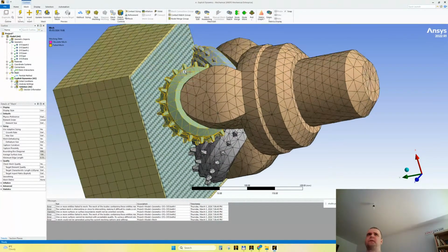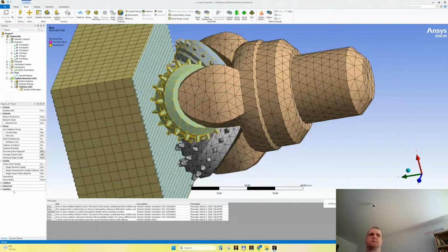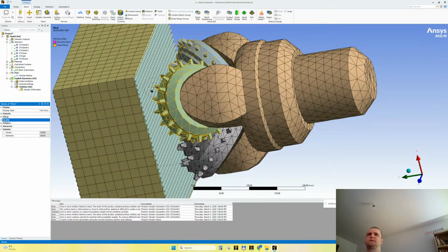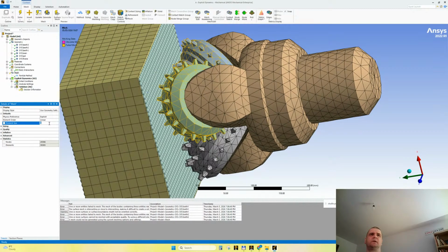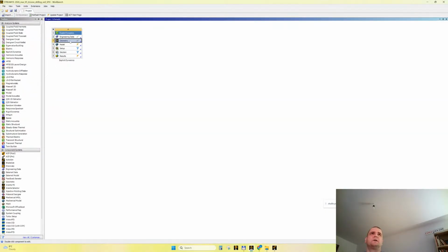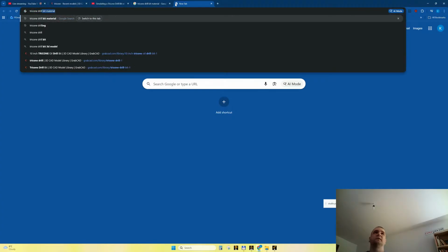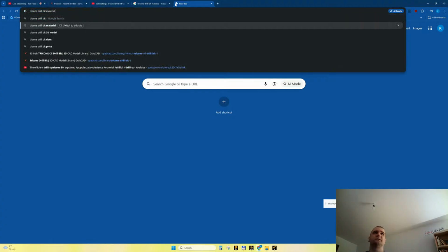So I like having coarse mesh because it will ensure we have around 30,000 nodes in total. It will ensure that we have a faster solving time. Now, let's go and assign a minimum size, let's say. I keep saying that I will scale the assembly, and I forgot it. Let's scale it. Do we have a dimension? Drill bit dimension. Click on drill bit sizes.